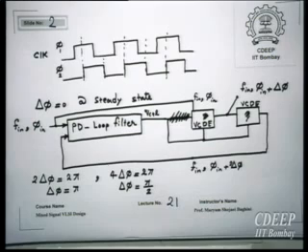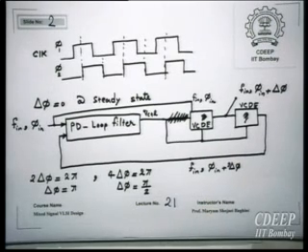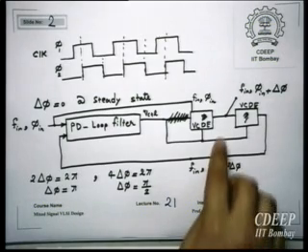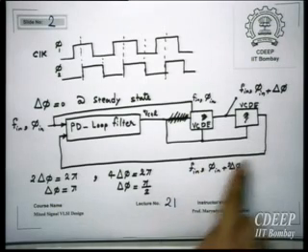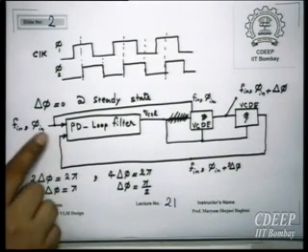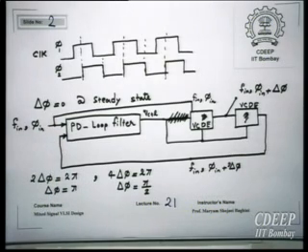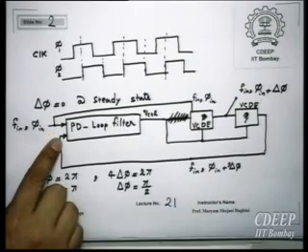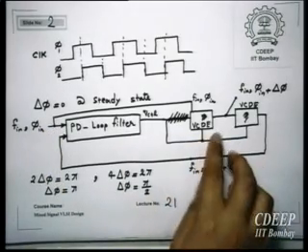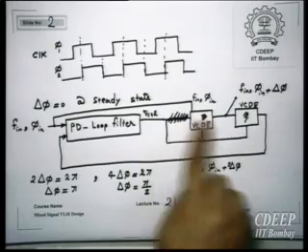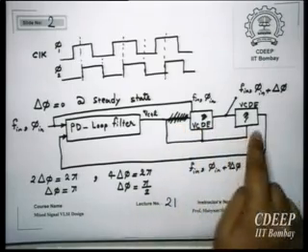Now this is one of the applications of PLL, but because it locks at a particular delay, in fact at what delay? The delay between these two phases is 0. So it locks at 0 delay between these two inputs, and therefore it locks at a well-defined delay between input and output of each one of these delay components.